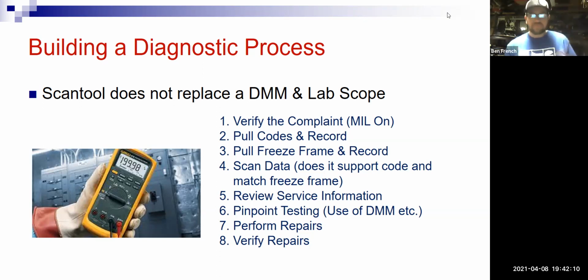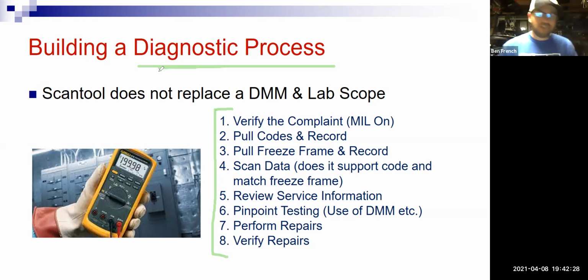Okay. So how do you attack this type of thing here? Well, what you want to do is go through these 8 steps here. Okay. Think of that great 8. Well, this is the great 8 steps to building a diagnostic. Okay. So whenever you have the customer bring you their car, I think very rarely did a customer bring me a car and say, "Oh, there's nothing wrong with it. I just want to give you money to look at." Right? There was always some type of complaint. So you get that complaint from the customer, and your very first step is to verify what that complaint is. Okay. What is the complaint?